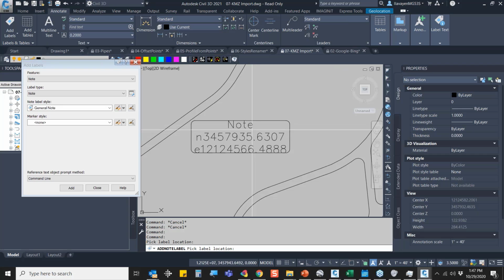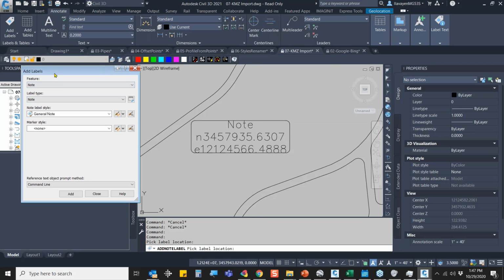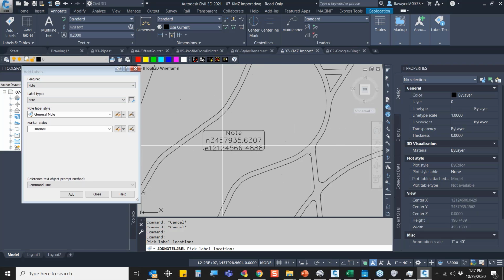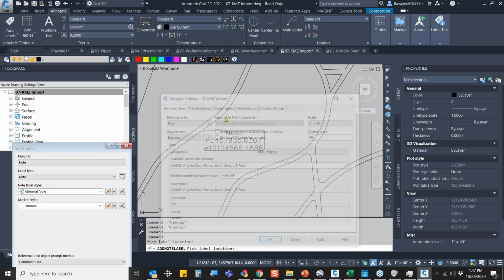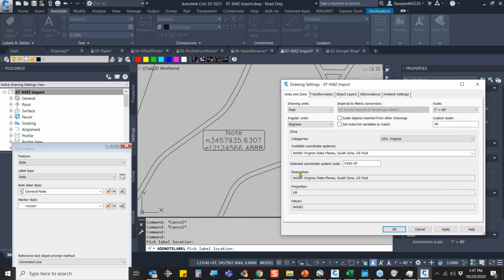And it places it on my current layer, and you'll see here that it is curves, and now it's basic elevation 0. So it really helps me with all my drafting, all that planimetric stuff, being able to do measurement, adding some hatches, maybe some trimming. It's a neat little tool set that helps me transition from that 3D line work to 2D line work that's usable for drafting. So you can see here it's all flattened out at 0. And there it is, the flatten and explode feature line.